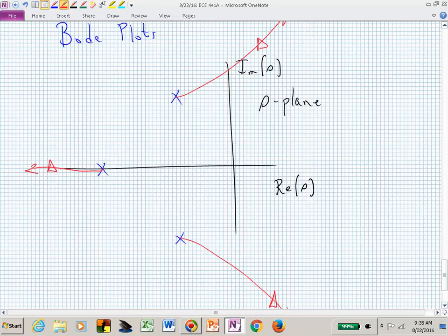What we are trying to do is make sure that we stay out of the right half plane. The right half plane, which is the right half of the complex plane, has real parts that are positive, and that looks like e to the t, e to the 6t. Those exponents are positive, and those are going to go unbounded with time. This would not be a good design.